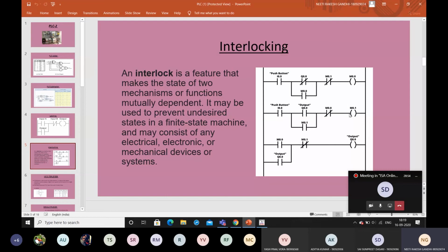time. And this is basically a latching function again, and let's assume that my output is a fan. So this is a fan that's in my first room. So when this light is triggered and this is shut, the fan of room 0.0 is also going to be on. So when this is triggered, the fan of my first room is automatically going to be on, and if my second room light is on, then the fan of the first room is automatically going to get shut.